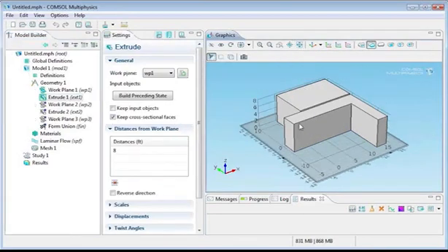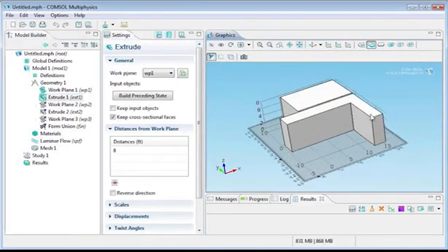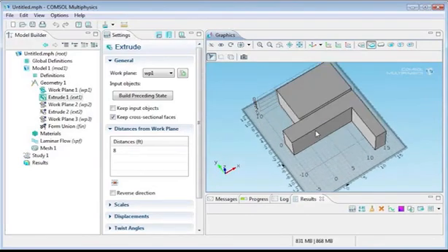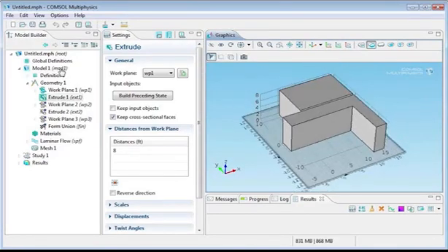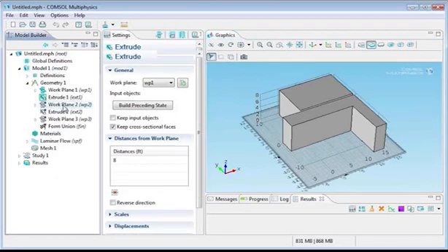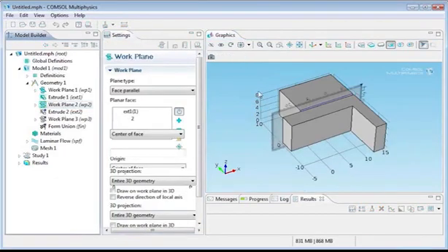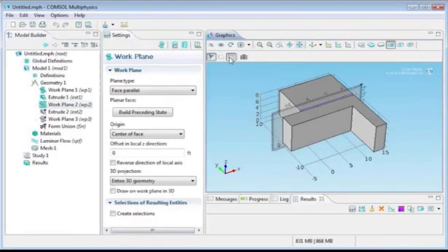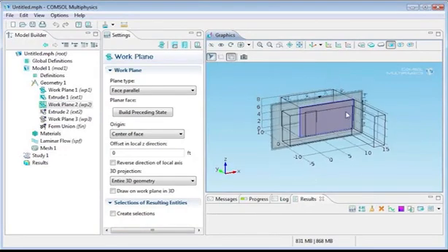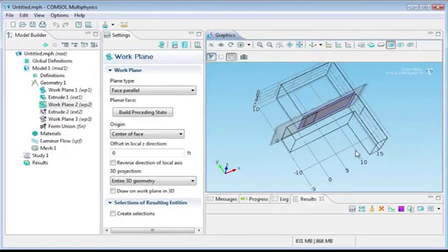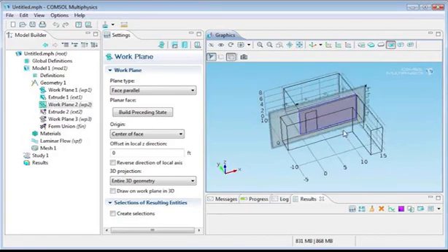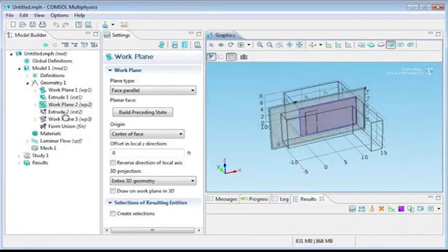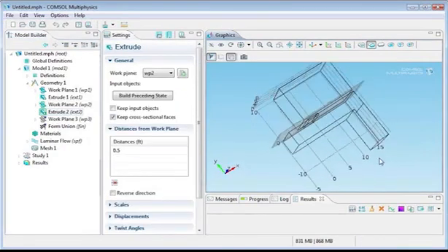And now we've got the structure of the hallway and the office, but we don't have any door communicating between them. So let's fix that. So I go to another work plane. I'll build that. In fact, let me make this wireframe so we can see it. There we go. And so you can see that what I did is I drew on the work plane of the office wall, I drew a doorway. And then we'll extrude that, and then the doorway is present.